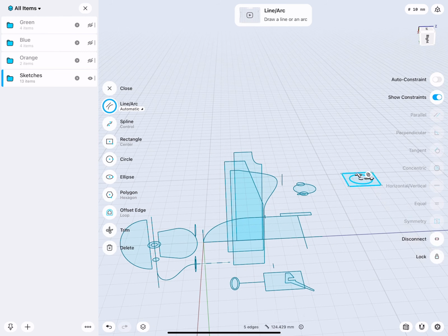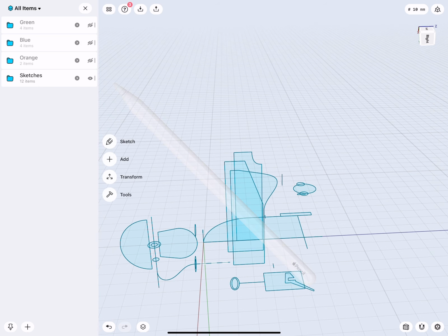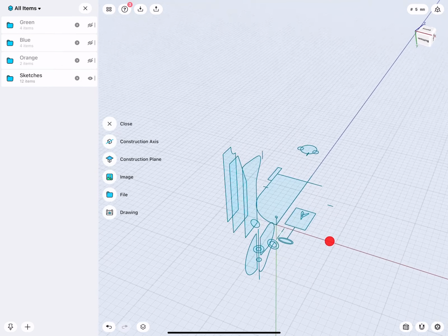That's the reason why I point this out first before we go into modeling: you don't necessarily have to first create a construction plane, offset it, and then put a sketch onto that construction plane, which is something we're very much trained to do in parametric engineering programs. The beauty in Shapr is that while we have access to construction planes, we don't need to. We don't have to put a sketch on a construction plane. We can simply sketch it somewhere and then just move it.